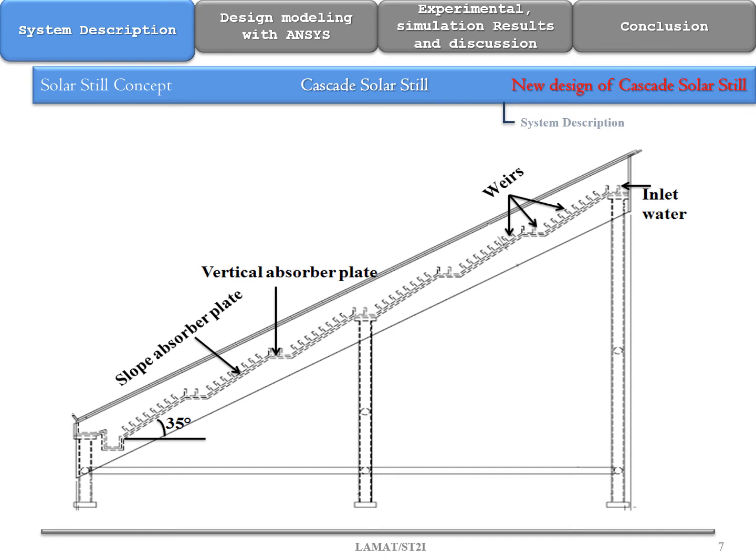was about 145 degrees. In order to improve the performance of the cascade solar still, the flow velocity of the water in the absorber plate should be minimized. Therefore, in the new design of the sloped absorber plate, we added different weirs to the surface of absorption.